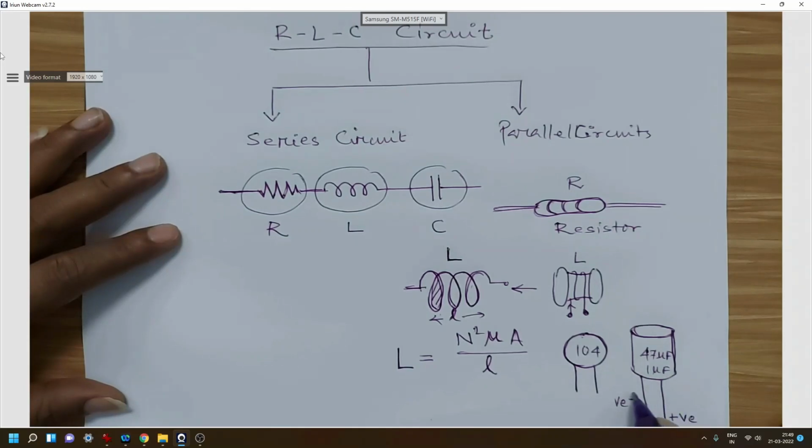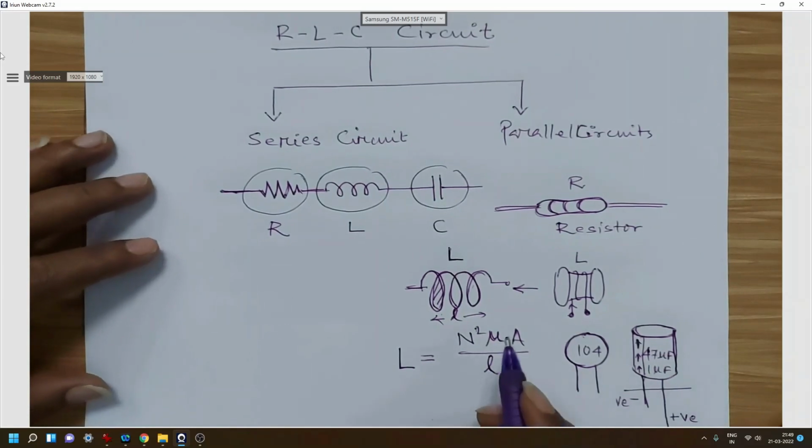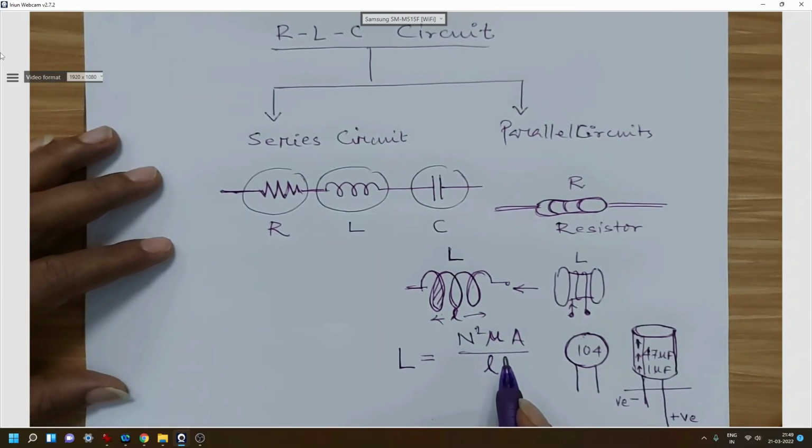Now if somebody has cut the legs somewhere during the connections, there will be no difference between the lengths. In that situation, we will also find a band with some arrows, and those arrows will be near the negative terminal. So you have to look for the band with arrows, which indicates the negative terminal; the other one will be positive. We have to know these protocols first, and then we will be able to connect in a proper way.